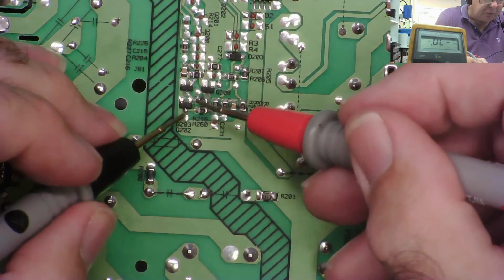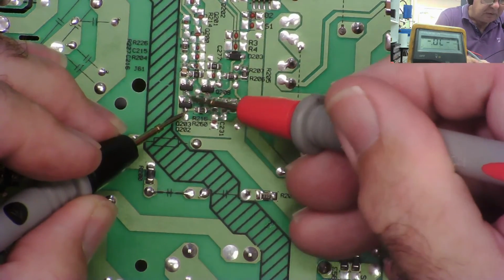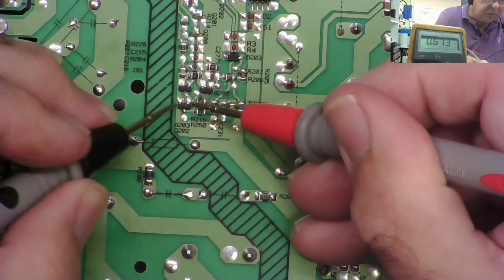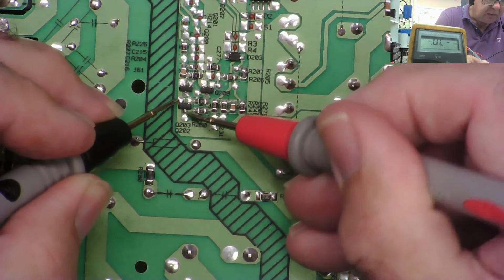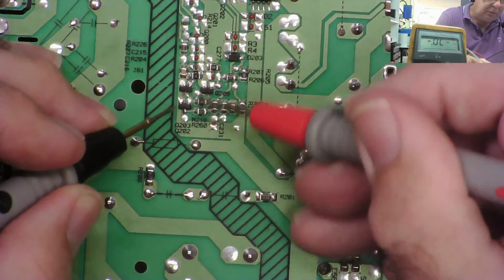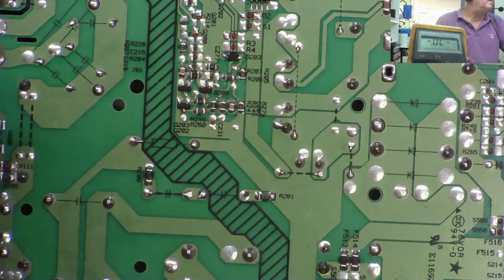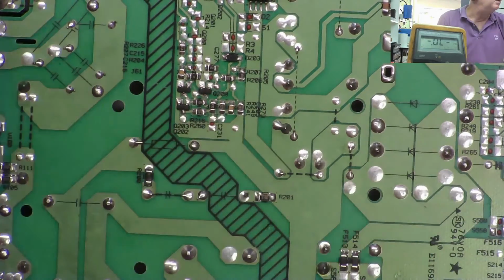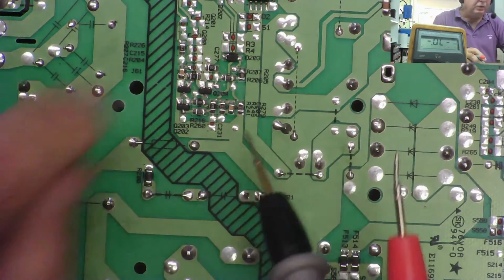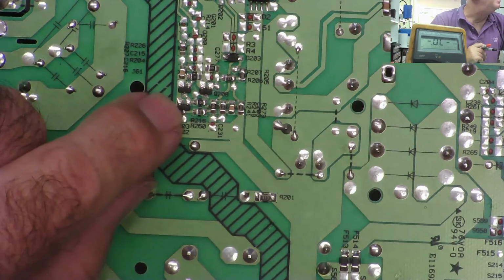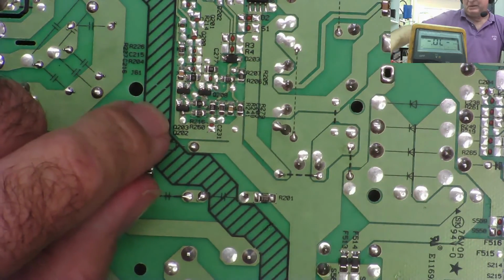The chances are they're all so close together, they're probably all interconnected. Junction there, junction there. That means nothing across that one. That one just reads like a transistor. So that one we can say looks good. These two, yeah, maybe. But as I say, not everything on three legs is a transistor, yeah? And certainly not a bipolar transistor.